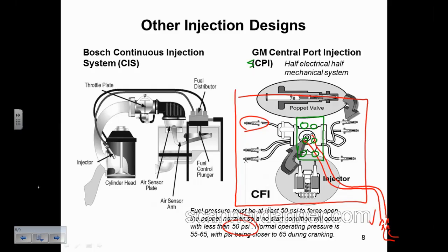Sequential was better because when a vehicle would misfire, if we could identify the misfiring cylinder, what can we do with that fuel injector? We can shut it off. And when we shut it off, we protect the cat, we protect the environment during a misfire. That was the advantage of a sequential, and it's more than that too. It's more precise, better control. But they went to a central sequential port injected system in 96. The V8 trucks, no big deal. Just add two more lines, two more poppets, and these were all buried under the manifold. You couldn't see any of it.